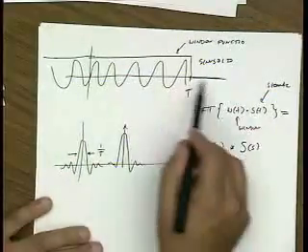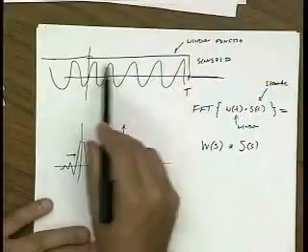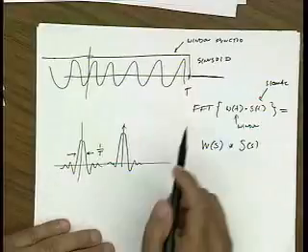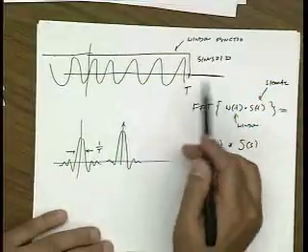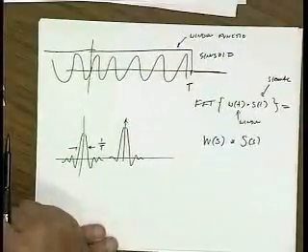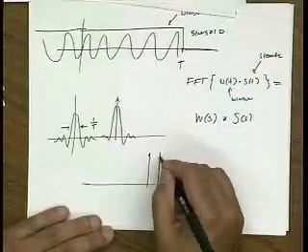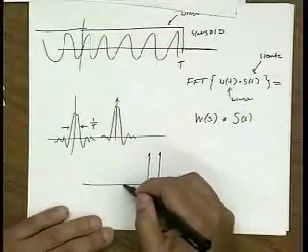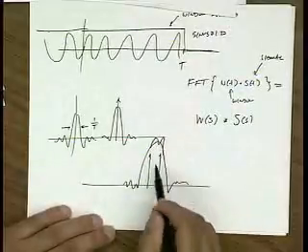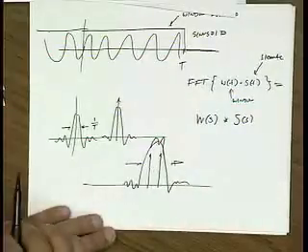Now there's lots of window functions out there. You don't have to use a square window. You can use windows that have less energy at higher harmonics so you get a nice peakier response. But fundamentally, this relationship with t doesn't go away. You need to make a simulation time longer and longer to be able to resolve two close frequencies. Because let's say I have two frequencies that are closer than the sinc function, then when I convolve my sinc function, they're going to run into each other and produce a big fat pulse rather than two tiny narrow pulses, right?